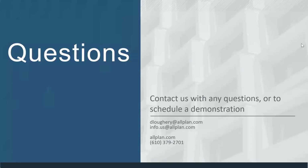This is a two-part question. How easily does the BIM model merge with models from other programs? And are there extra steps needed to have models merge correctly? We import and export many different file types. So any 2D, 3D data that you want to get into or out of ALLPLAN, you absolutely can. IFC is the go-to standard. It's a common data environment for all platforms, all of the softwares, and it's meant to be merged with other models.